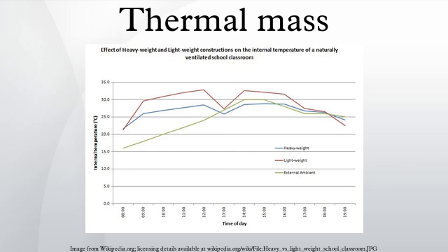Background. The equation relating thermal energy to thermal mass is Q = Cth ΔT, where Q is the thermal energy transferred, Cth is the thermal mass of the body, and ΔT is the change in temperature. For example, if 250 J of heat energy is added to a copper gear with a thermal mass of 38.46 joules per degree Celsius, its temperature will rise by 6.50 degrees Celsius.